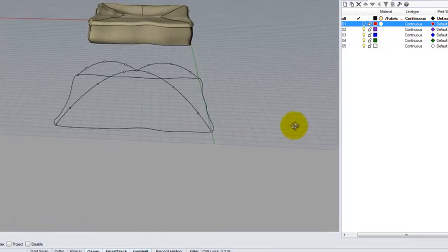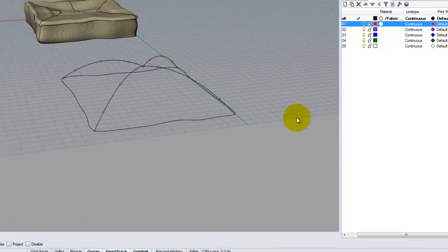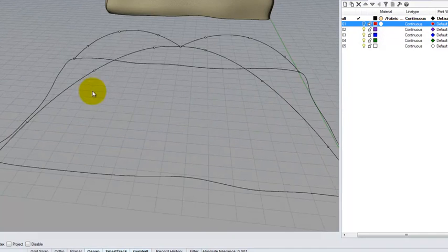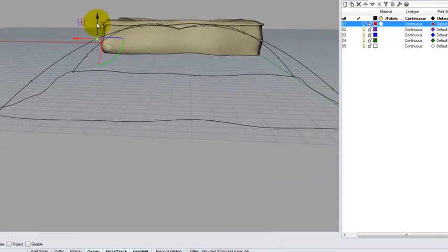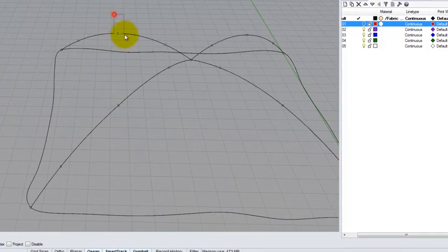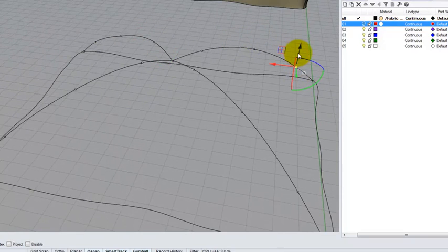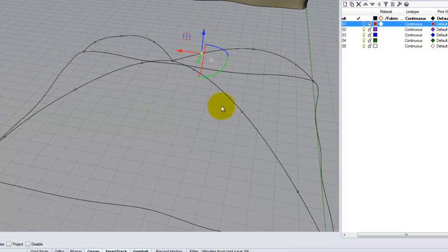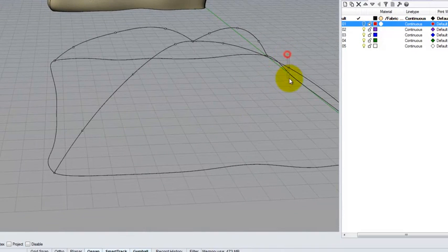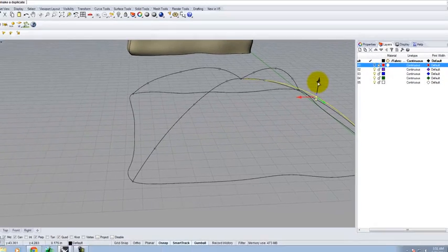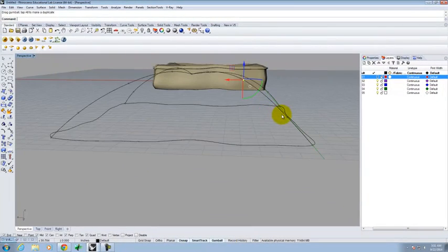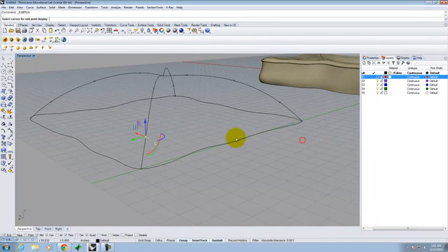Something like that. Okay, so you see how I'm creating that side of the pillow? Makes sense so far? Okay, we need a little bit of variation. They can't all be perfectly identical, so we'll create a few little dents. These pillows tend not to be perfect. Right? If we want more dents, this is going to end up being a fairly smooth pillow. If I want more dents or more wrinkles, it's just a matter of rebuilding these curves with more points, and then I can work with them.